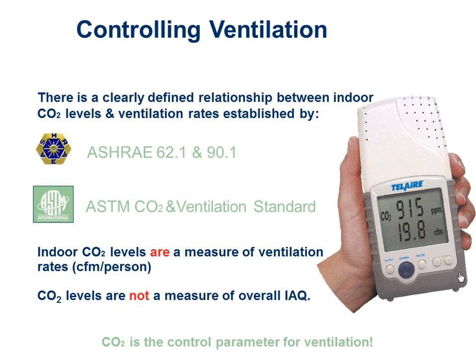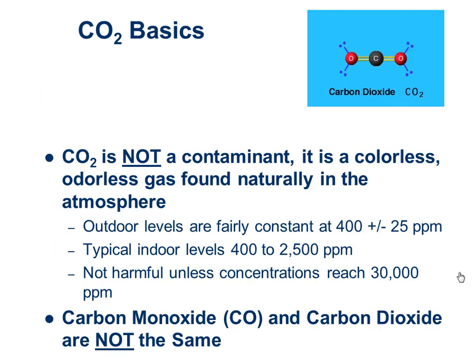And as you're going to see here in a little bit, ASHRAE advocates using CO2 sensors to ventilate spaces, and in some cases it's actually required. I want to point out, though, that CO2 sensors are a way to measure how many people are in the space, or more accurately, how many people are breathing in the space, and they are not an indication of direct indoor air quality. Indoor air quality is a function of many factors, and it's not just the people and the outdoor ventilation rate. There are other things that could be going on in the building that are improving or decreasing the indoor air quality. So this is just a way to measure how many people are there and correlate that to how much ventilation the code will make me bring in.